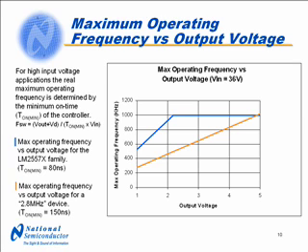Shown in orange is a competitor device with a maximum rated operating frequency of 2.8 megahertz, yet this device has a minimum on time of 150 nanoseconds. So if the input voltage is set to the maximum of 36 and the output voltage, for example, is set to 3.3, this device can only operate at 700 kilohertz, far less than the claim of 2.8 megahertz.